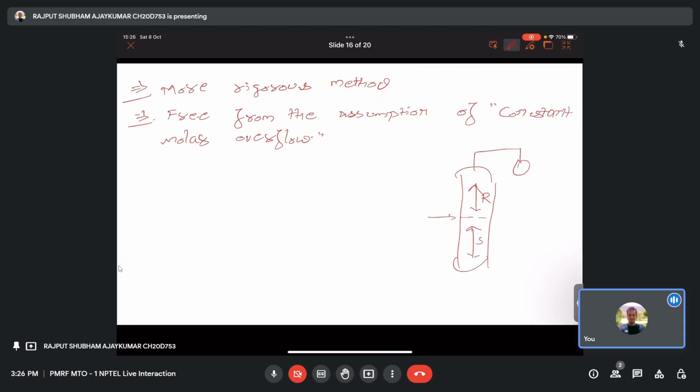There will be a condenser to accumulate into a condensate drum. Half will be reflux and half will go out as distillate. Similarly here there will be a reboiler, where some will be turned into vapor, and the rest will have a concentration.